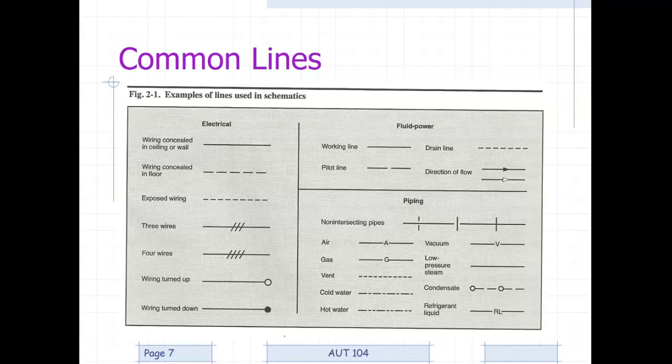Whenever you take all the air that's got all this water and you start compressing it, basically it'd be taking a damp towel and you start balling it up into your hand and compressing it in your hand. What's going to happen to all that water? It seeps out. Do we want that water in a pneumatic system? No. So what do we do? We drain it out to the best of our ability. That's the biggest thing with pneumatics, you've got to make sure you keep that drained out, because if you don't, it will make you regret it, if nothing more than with rust. Rust is never pleasant.